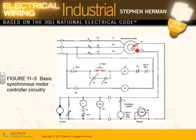They put DC value from a DC machine, and that condenser, and they close these contacts and run them unloaded, no load. When I say unloaded, guys, there is no mechanical load. It's not a fan. It's just a rotor like this, rotating. This is a control system for it, so it monitors the power factor and corrects it. Any comments, any questions about condensers? They call them condensers, synchronous motors. Think of them as capacitors.